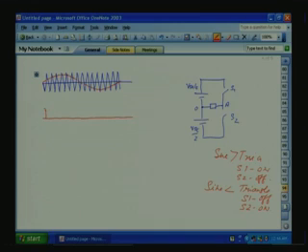Then during this portion here, sine is less than the triangle, so you will get minus VDC by 2. So our pattern will be like this, and the width of the pattern in a triangle period varies proportional to the amplitude of the sine wave. That means the area of the portion increases sinusoidally.